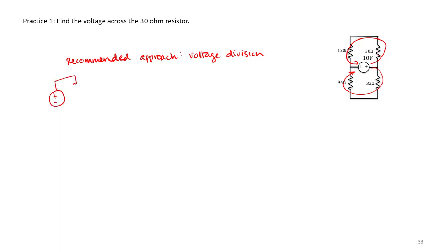Another way to draw this circuit is to draw 2 sets of parallel resistors. And if you walk around this circuit in both loops, you'll recognize that this is indeed an equivalent circuit. So in this case, given that both the 30 ohm and 120 ohm resistors must experience a 10-volt voltage drop, we can actually consider those resistors separately.